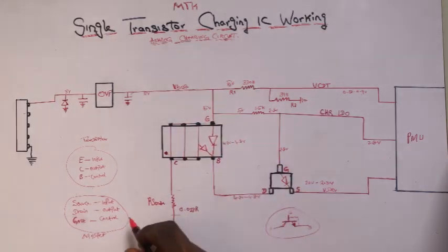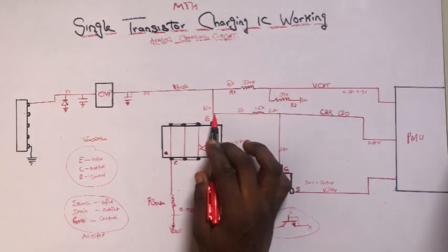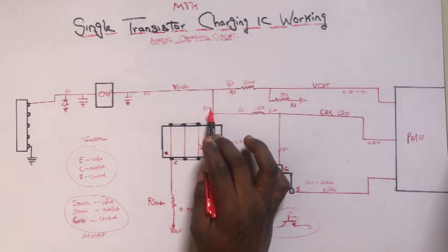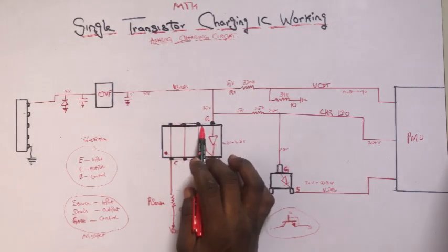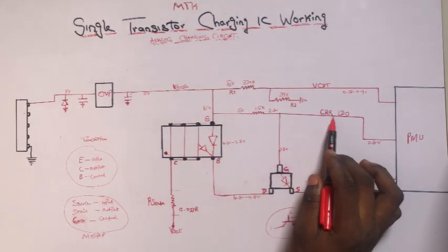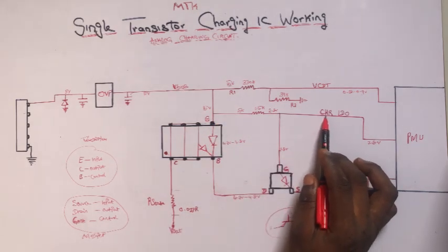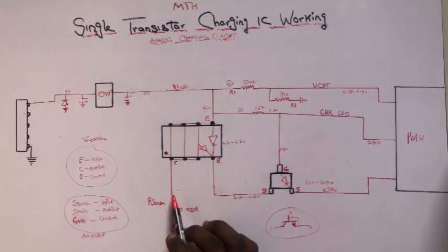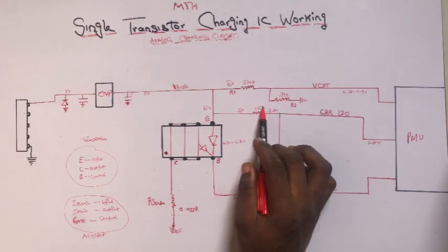So now let's move to the next line without wasting time. When we get to the next line, we will have another line that comes out from the same 5 volt line, from our VBus line. Another line comes out, and it is called charge LDO. That is charging low dropout. It goes to our power IC. There is a resistor connected in series in this line.